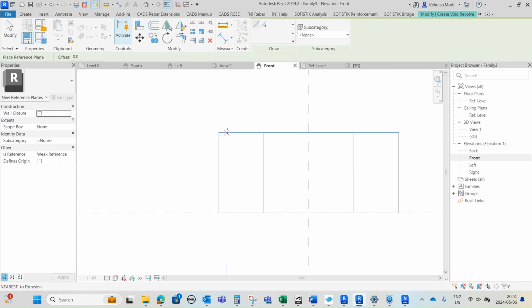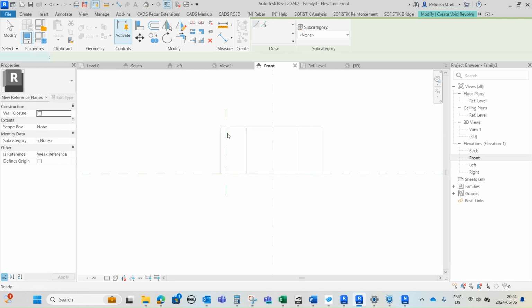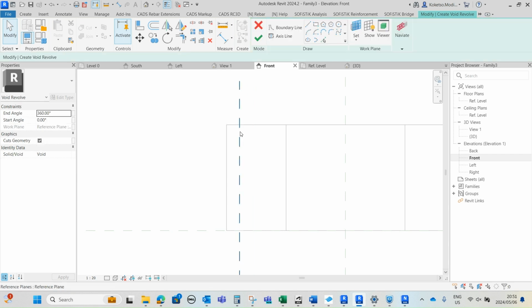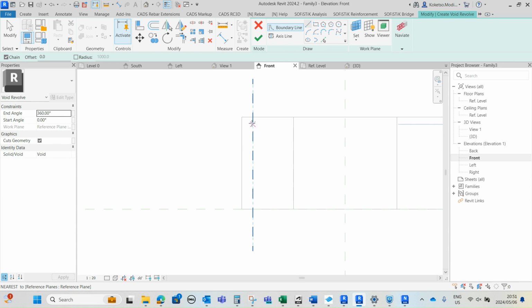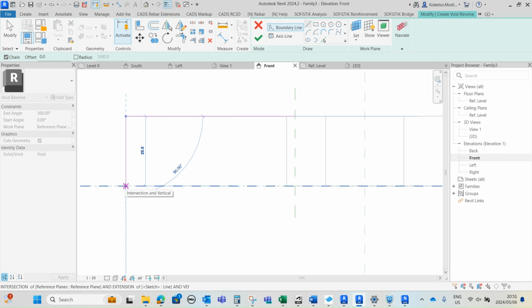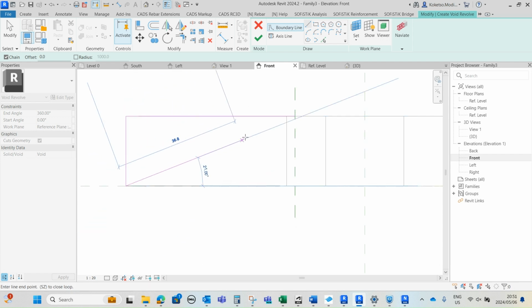It's a reference plane, and then I'm just gonna randomly place a reference point this side. I'm gonna select it, and then from the edge of this polygon, I'm gonna offset it by, let me just make it 5 millimeters and see. Actually, okay, let me make it 2.5 and press enter. And then I'm gonna select my line, place a rectangle like this. So I'm gonna make it 50 millimeters and then bring it down by 20 millimeters, and then I'm gonna take it diagonally to the first insertion point that we started from.